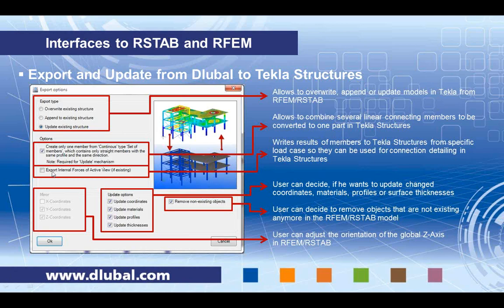I can also update the Tekla model with additional information like internal forces, and these internal forces can then be used inside Tekla Structures to have a better idea of what type of connection and which type of bolts and thickness of plates I might have to use. So Tekla has the option to display internal forces, and we can fill these fields with the correct values from the calculation.